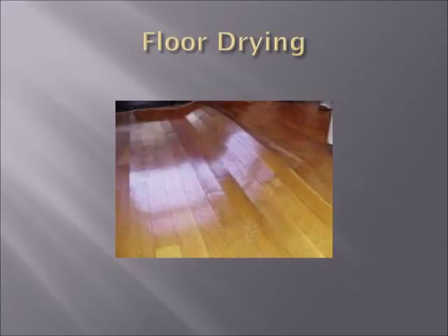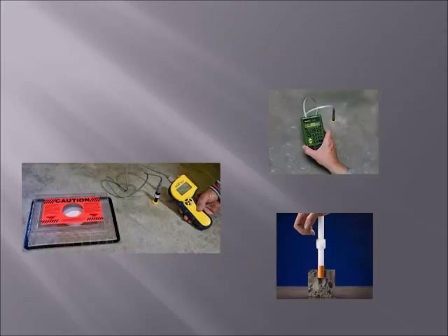Floor drying or moisture vapor emissions is another topic that does come up from time to time. Structural lightweight concrete may take slightly longer to dry than a normal weight concrete, but has not been shown to be significant. There are many other reasons that moisture may be present longer. It could be due to not protecting the concrete, allowing it to become re-wetted. It could be the use of some type of a curing compound. There are many ways to check this out in the field.